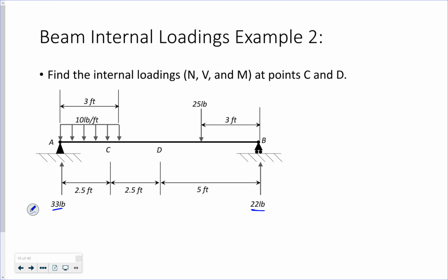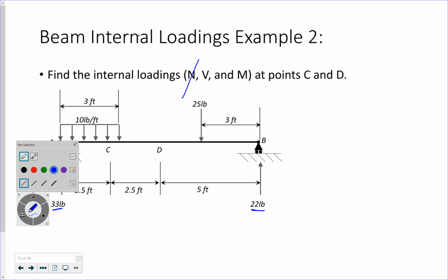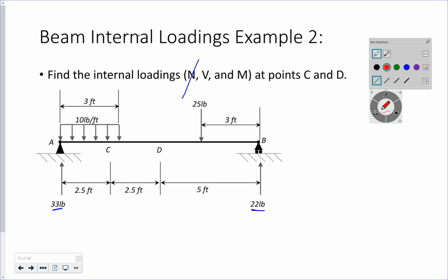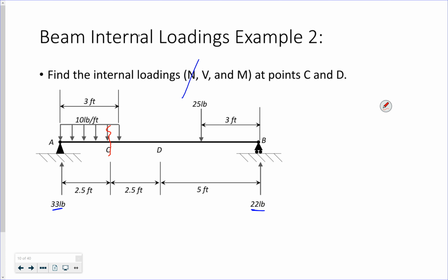So internal loadings, again, I'm going to ignore that axial load. And I want to know at C, so I'm going to cut it, which happens to be not in the middle of, but in my distributed load. So let's do C together, and then I'll let you do D on your own.